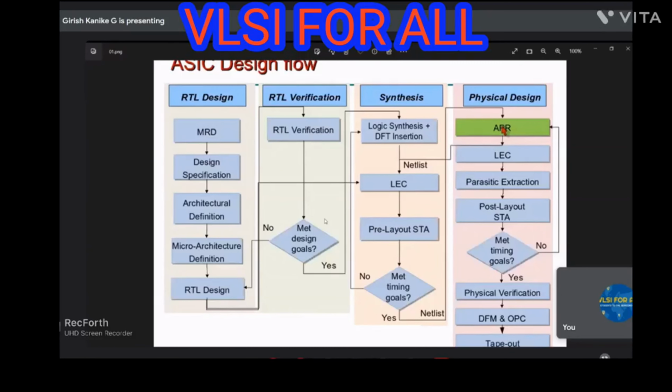Okay, after this netlist is there, we'll do some checks here. Now the logical equivalence check will be done, meaning the logic will be checked here. So if you have an AND gate, the AND gate logic will be checked, meaning what the AND gate logic is. If you are giving similar inputs, that's 0 0, you need to get the output 0.